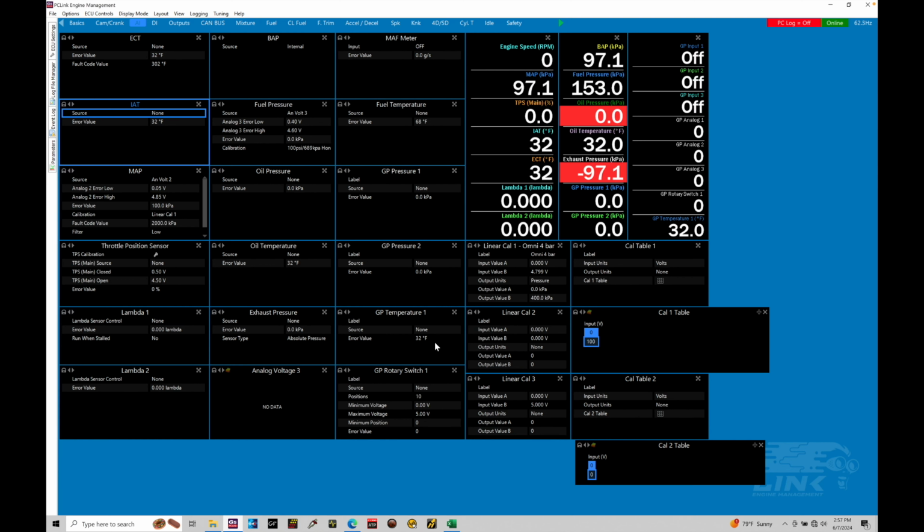Okay, let's first set up engine coolant temp and intake air temp here within our window. First things first, engine coolant temperature. I'm going to set this up because this is the very first one on the list. Now I know where I've wired my engine coolant temp and intake air temperature in terms of the inputs to my G5 box. I've actually wired engine coolant temperature into my analog temperature 2 input and my intake air temperature to the analog temperature 1 input. So I know where those pin designations are for both temp sensors.